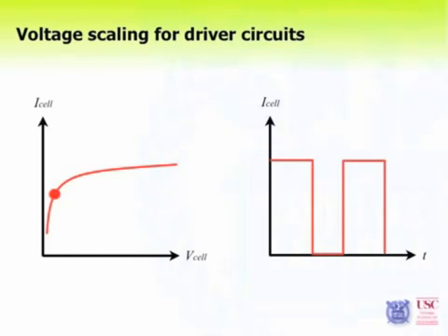Supply voltage scaling directly affects the cell current. With decreased current, we can achieve the same average current by prolonging the turn-on duration of the switch, which is done by image data modification. We call this process image compensation.